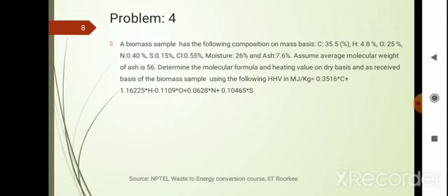So first, we have to calculate the molecular formula of the biomass. Why is this molecular formula required? Every biomass or petrol or diesel and everything, we can write as some CxHyOz, etc. If you obtain the molecular formula, we can calculate the stoichiometric air fuel ratio. That is very, very important. We will study it in later sessions.